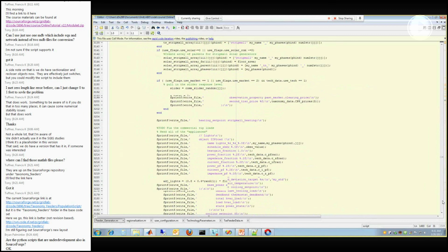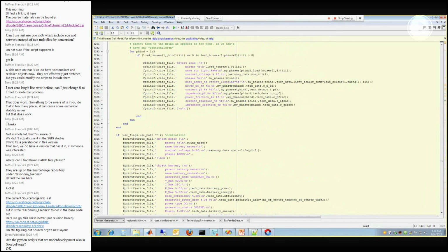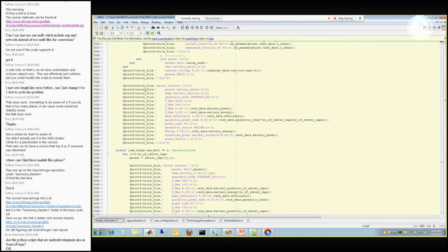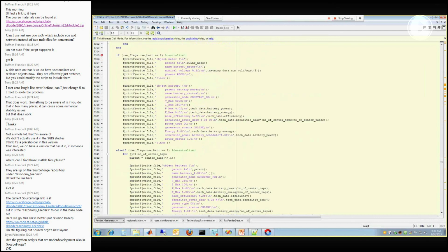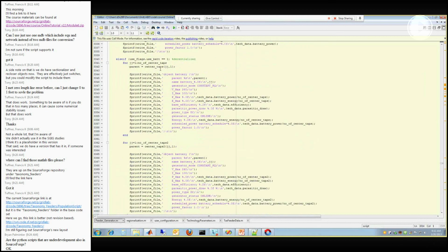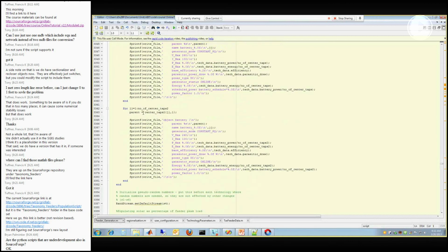What I want to get to is the next piece: once we're done creating all these houses and the street loads, or light loads, there are other things that we have to create. For example, here is where we start the actual battery creation. If we wanted to do a battery model, we would add this battery on, a centralized battery versus decentralized battery. So we had to capture the information about where we could populate decentralized batteries, i.e., where all the center tap transformers are, and what the different names of all the center tap transformers would be, so that we could parent the battery to those different locations.